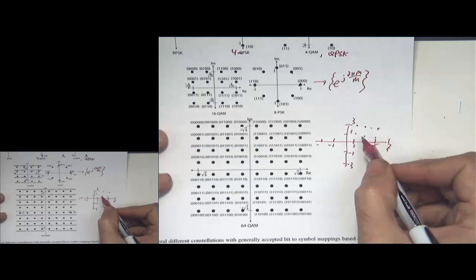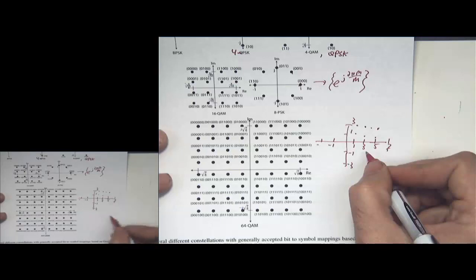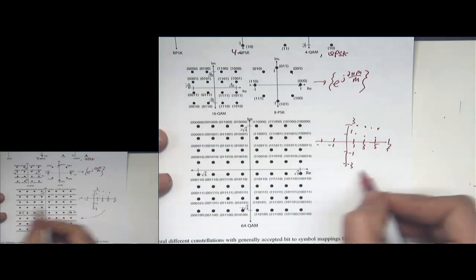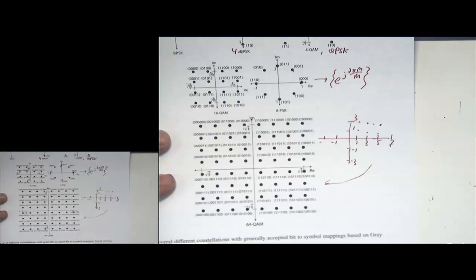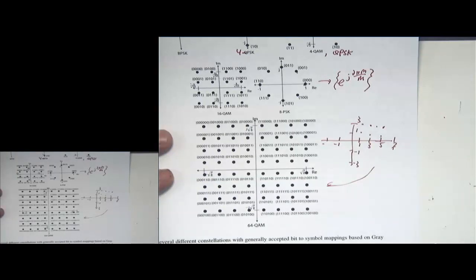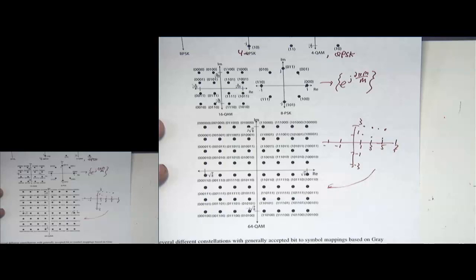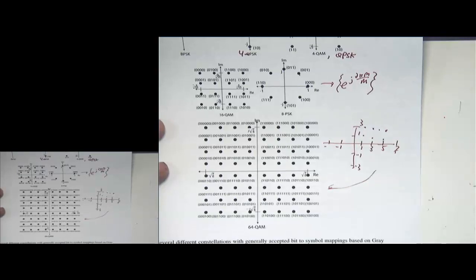So it's going to be plus minus 1, 1 plus j, 1 plus 3j, 3 plus 1j, and so on. And then you apply a normalization to get what I have here, and to do that you have to follow the procedure. In 802.11, for example, they actually specify the scaling factor. They use a slightly different scaling factor because having something like a square root of 7/6 would be inconvenient to compute, so they tweak it a little bit. So it's not quite unit energy.